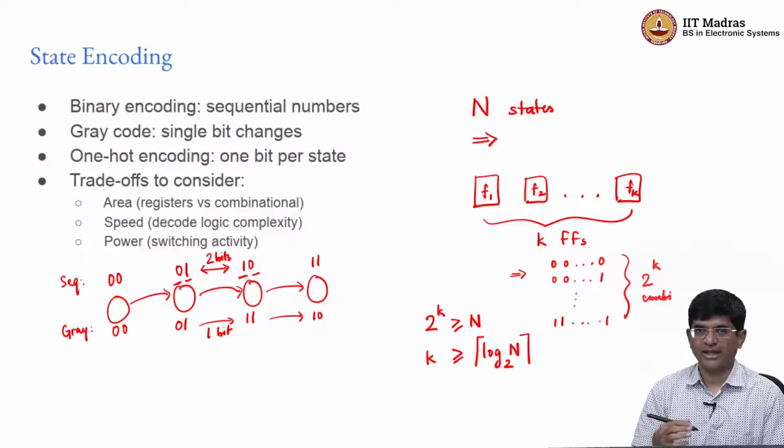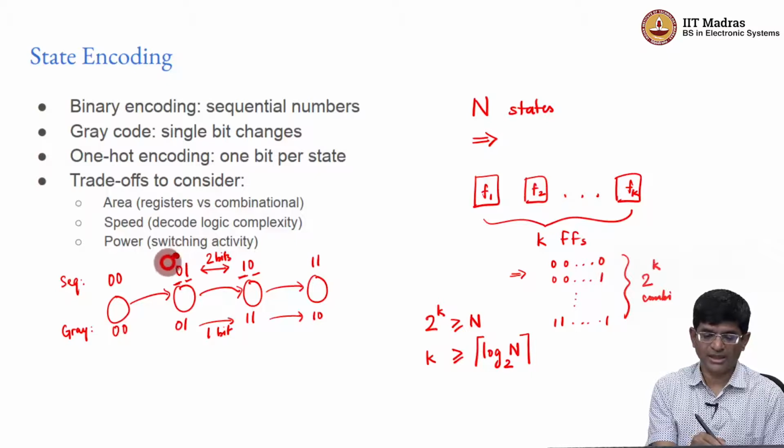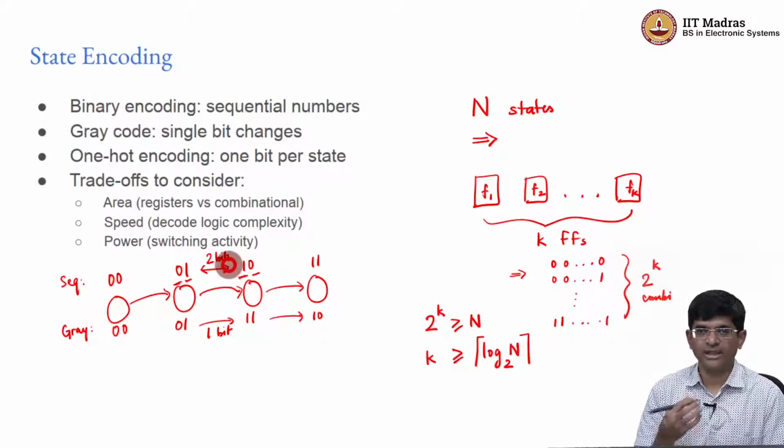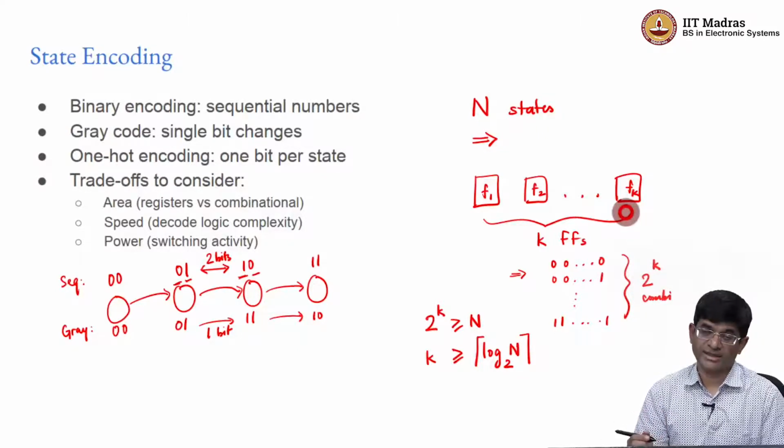Now, if I had an output state encoding which is multiple bits like this, I would need to effectively have a decoder which tells me that I am in this current state, and therefore I have some other signal that basically activates and says, okay, I am in this state, therefore these outputs should become equal to 1. Whereas with a one-hot encoding, where only one of the flip-flops has a non-zero value, that decoding is almost trivial. It is trivial in fact, right?